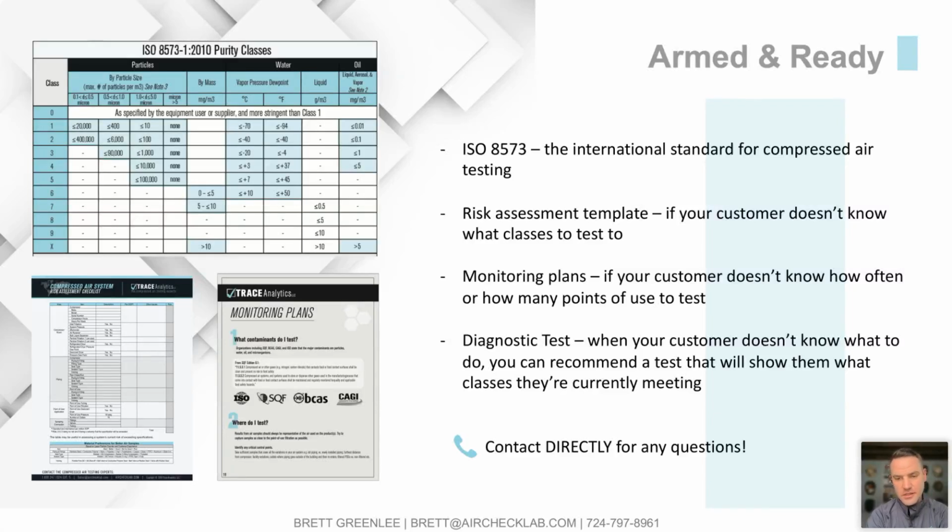So this diagnostic test is a great way to grab a glimpse of what your compressed air system is doing now and tell you what it's performing to now, and what purity classes you are reaching for particles, water, and oil, and those types of contamination. And then we can partner with your service provider to make improvements, to put some of those preventative measures in place, to act upon some of those alert levels and actually maybe identify what they're going to be.